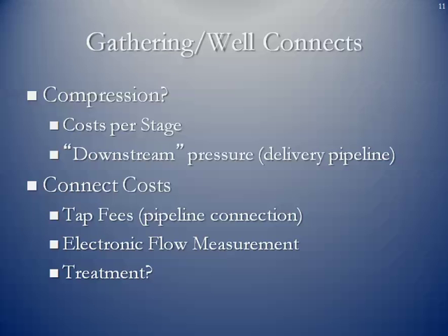In terms of how you would connect these, a question might be whether or not you do need compression, and that's going to be a function of the pressure downstream in the pipe into which you wish to flow your gas. And then we have to also recognize that there's going to be costs. The more compression that you use, that you have to boost up the pressure of your well relative to the downstream pipeline, it's done in stages, and there's going to be a cost.